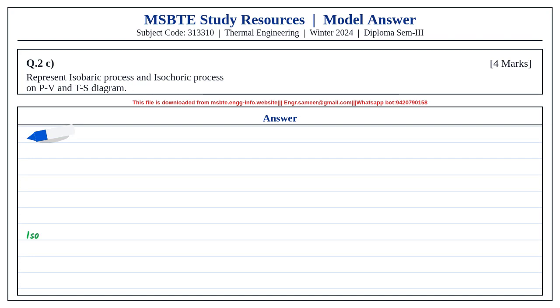Substituting this value, we get P1 V1 by T1 is equal to P2 V2 by T2, which is constant and equal to R. For mass m of gas, PV by T is equal to mR. Therefore, PV is equal to mRT, which is the characteristic gas equation.